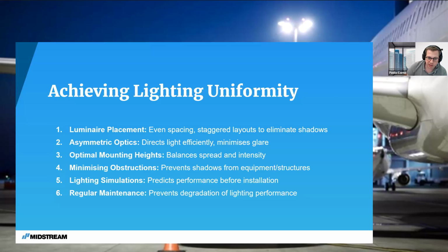While if you try to achieve uniformity by using many symmetric beams, you're effectively lighting some parts of an apron exclusively with one or two luminaires. And you sort of try to compose this uniformity by composing a puzzle of light distributions. This is definitely not ideal. Also, every distribution is going to have its peak and its decrease, peak and decrease. So your light uniformity ratio might look good on paper, but might not look great on the field, actually.